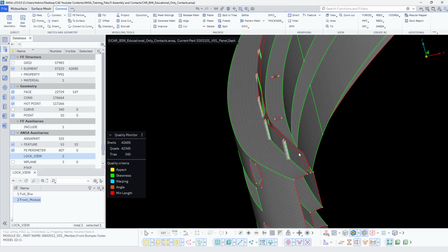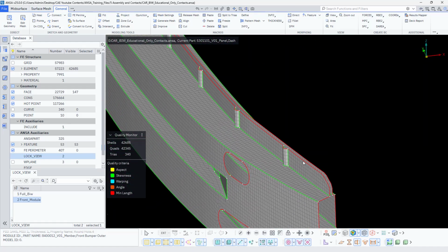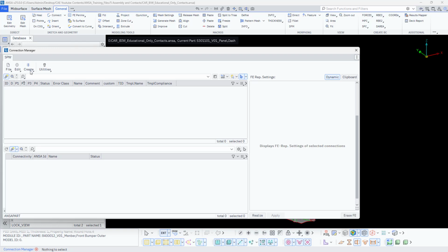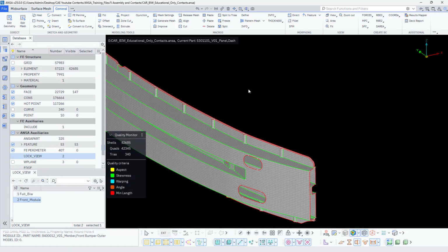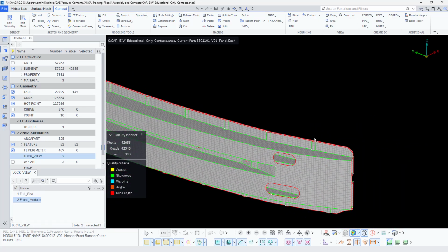Now, in between these two components, assembly or subassembly, I would like to create the spot welds. For that, in 24 you will have a tab here for the connections. In the connection manager, we have create, define manual, everything. Okay, and in the utilities we have convert and more. Just remember this. If you want, you can even activate this, bring those tools here and start working. But right now, as I don't have any connections recorded here, I need to create them manually.